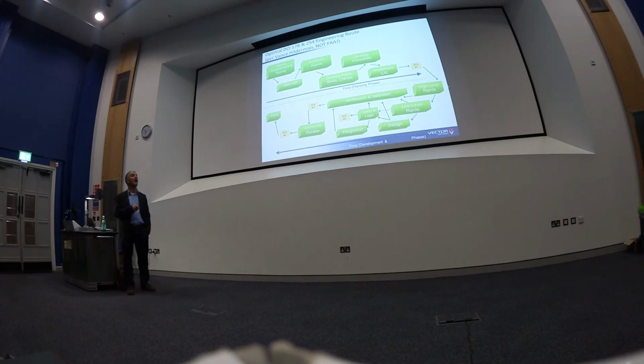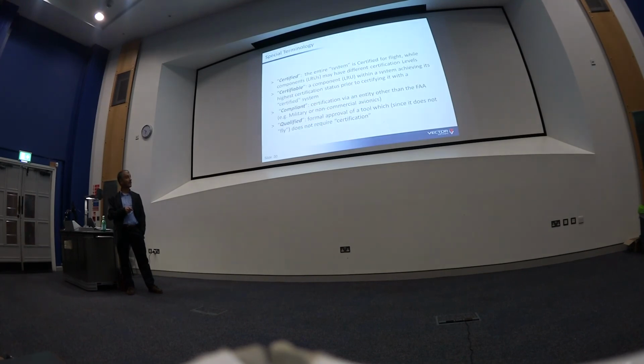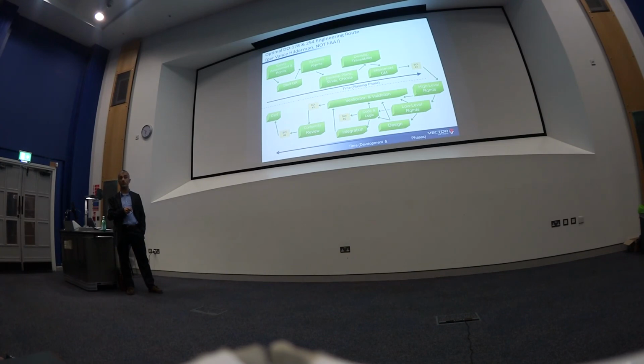And then you have higher level requirements, lower level requirements, design, code, logic, etc. And then you have SOI2. SOI2 is stage of involvement number 2, a development gate. Here you should demonstrate to the certification authority that you are doing well from a development point of view. So you are doing all the correct objectives for the software aspects for the development.